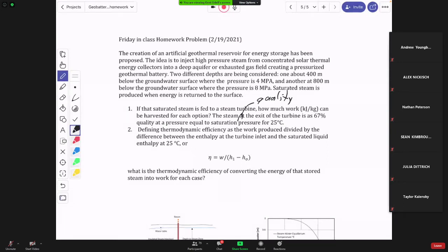We're looking at 4,000 kilopascal, right? 4,000 kilopascal is 4 megapascals. So you go to the pressure of 4,000, and you look across that, you see, I gave you a hint, 250, right? Oh, 250.35. And you go all the way over to the enthalpy of the vapor, and it's 2800.8. I completely was looking at something totally different. My bad. Yeah, that's okay.